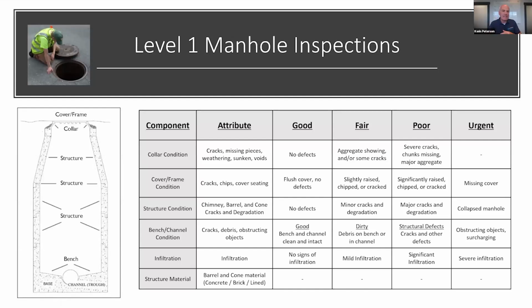In order to run this test, we have to open every manhole. And as long as we have every manhole open, it's a great opportunity to do a visual inspection of the manhole. And again, a lot of you are doing these visual inspections. We've got a form. Well, we're going to jet, and while the jetting is going on, we're going to do a manhole inspection. We'll capture that on a form. That's really important to do. It's the basis of our asset management program.